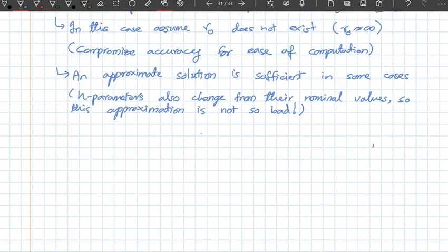So with these new assumptions, we can try to obtain the new circuit. So we have the new current source. You can use it as voltage controlled or current controlled, but we don't have the output resistance R out. Now we assume it is 0.